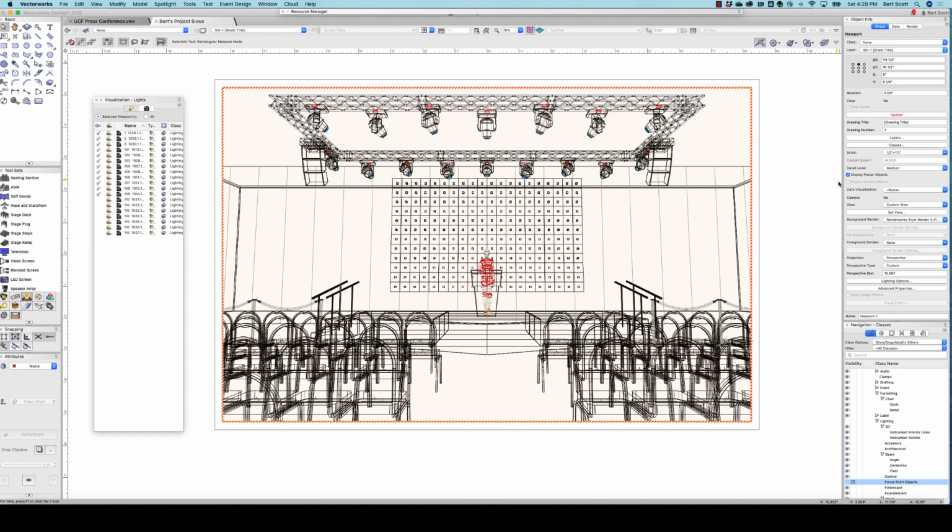So if you already know in advance, try setting it to the quick render that we just adjusted to see if that will work. Basically, the difference between the quick, the working, and the final is the settings where you can set things to low, medium, high, or very high. Final is set to high or very high, working is sort of set in the medium, and quick is set to low. That's what the big difference is.